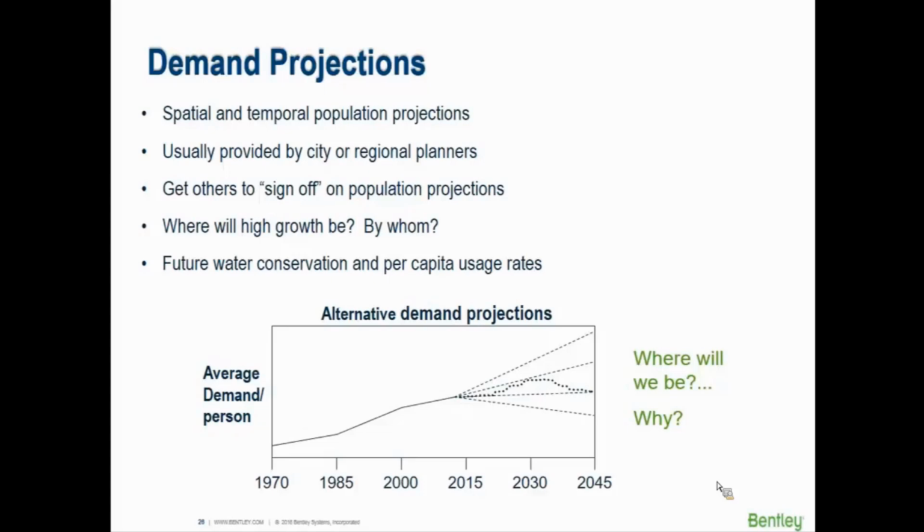Different countries, the demand per day per capita is different based on living conditions, based on whatever the needs are. But when you're looking at a future hydraulic model for, say, 2040, do you project that the demands per capita per person are going to be increasing steadily, will be linear, some innovative technology will come online and reduce it, or are you implementing drought water restriction plans for a city henceforth? So you anticipate gallons per day per capita will be decreasing, although population may be increasing.